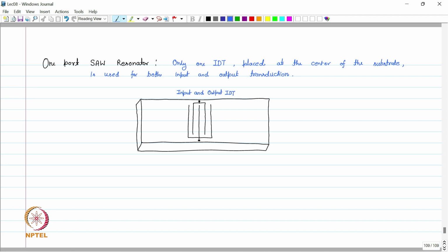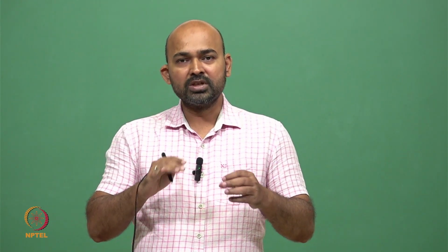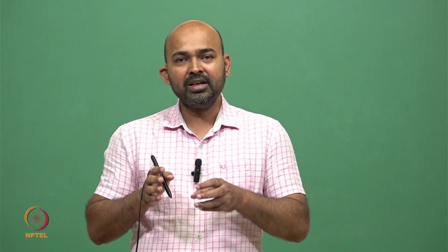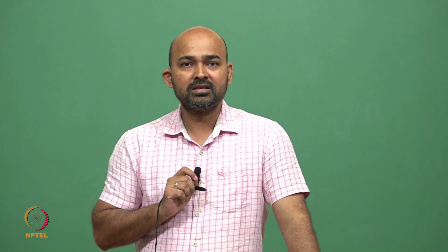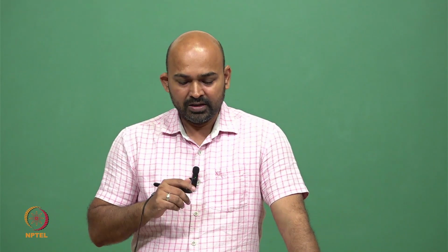So here we have this piezoelectric substrate. On top of this, we fabricate only a single IDT structure, because we know that a single IDT structure can be used to generate an acoustic wave from an electrical signal, and the same IDT can be used for acoustic to electrical wave conversion. So this will do both functions, input and output.